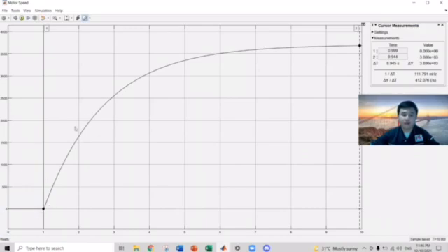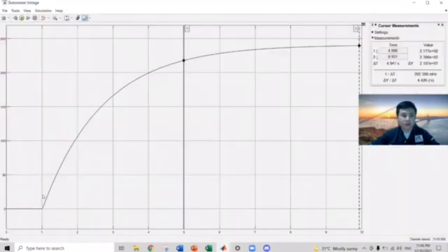For the motor speed, as the voltage rises at 1 second, the motor also starts moving after 1 second, and it rises slowly until a constant speed of 3,686 revolutions per minute. For your information, this motor has a rating of 3,700 RPM. This proves that the motor has achieved its break speed. And for the tachometer voltage, we can see the maximum tachometer voltage at 10 seconds,